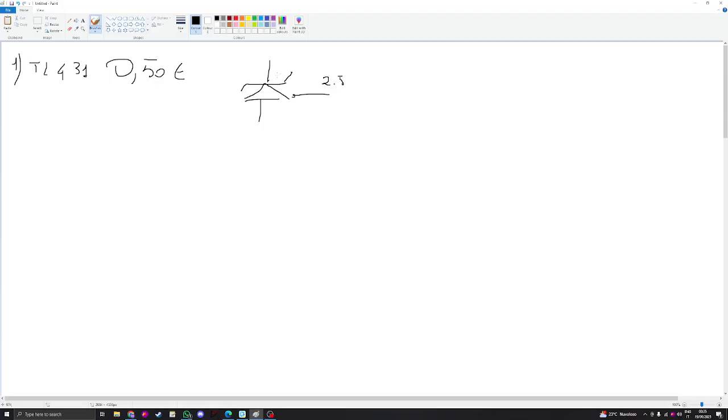If you provide a bias current of 1 milliamp with a resistor, and you have two resistors, let's call them R1 and R2, you already know the equation. This is Vref, this is VO, and for the divider, VR is equal to R2 times VO over R1 plus R2.